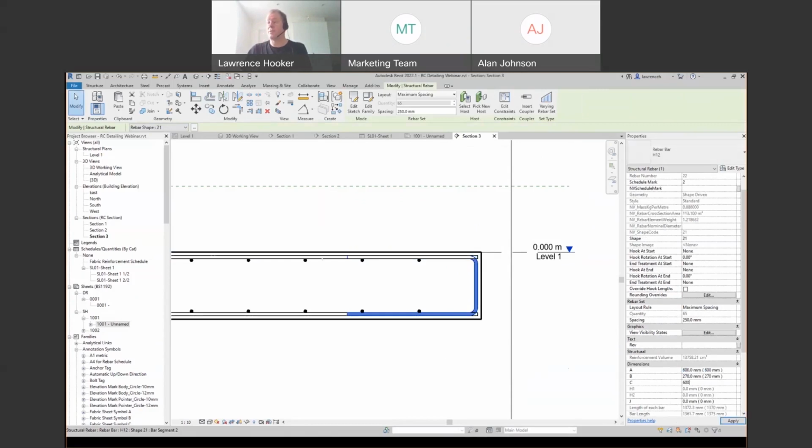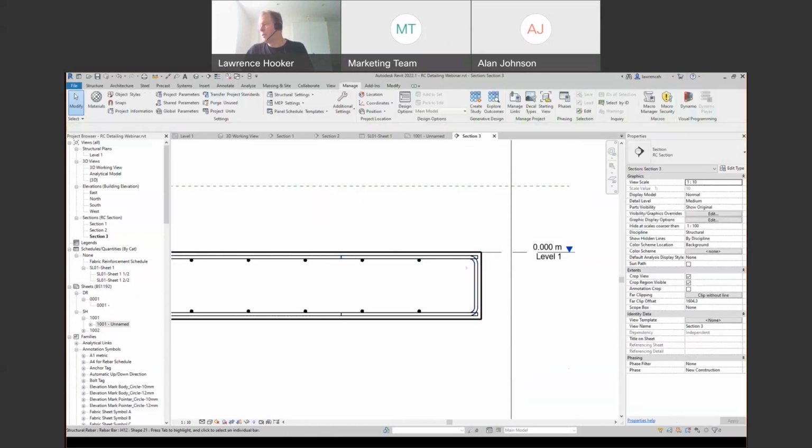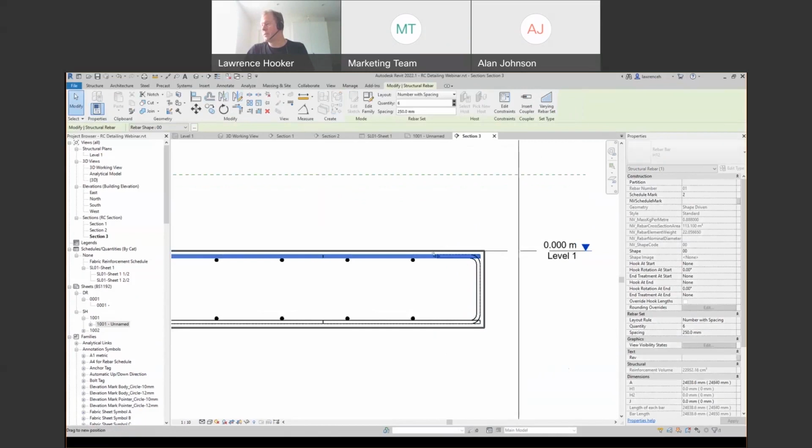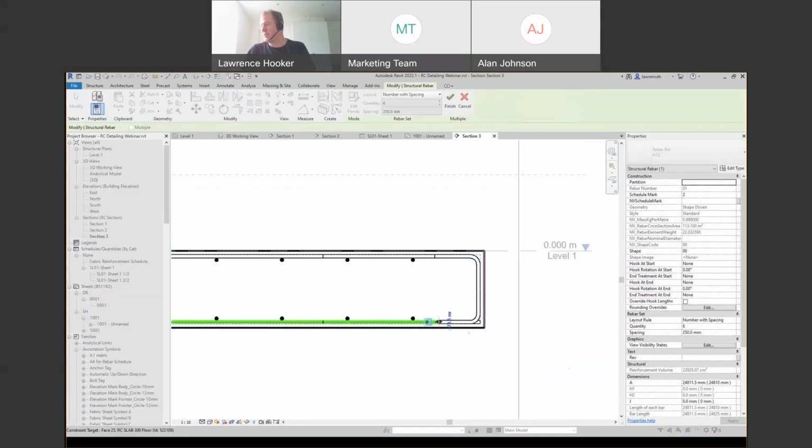Of course you could also constrain those as well to again achieve a lap. We can also constrain the layers in here as well. So if I don't want those layers to go right to the edge, we can obviously pull those back as well. And again, to get that accurate, I could go to edit constraint, as you've already seen me do within the context of a slab. And there I could say, right, well, that's got to be a 150 in there. And straight away, I can do the same thing up over here. Notice I can do it in the same command, which is the new function, negative 150 again. And then just simply finish.